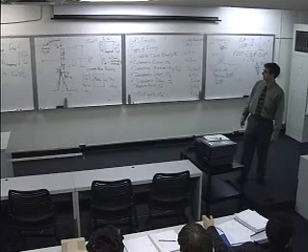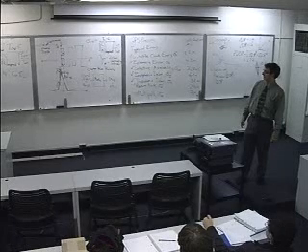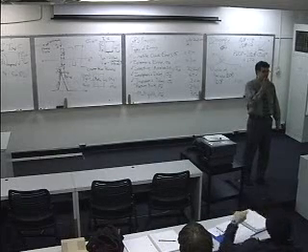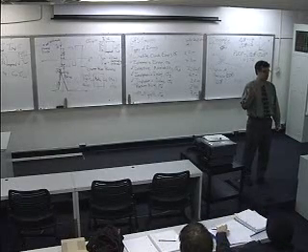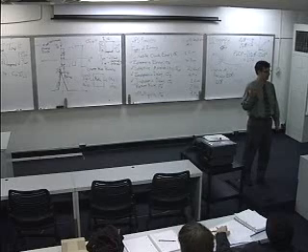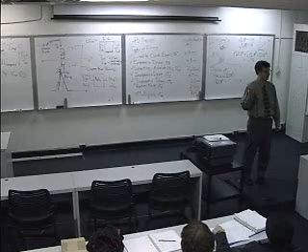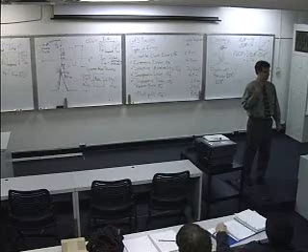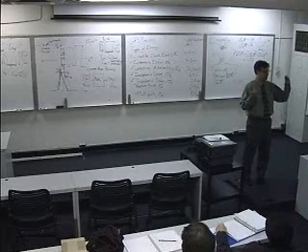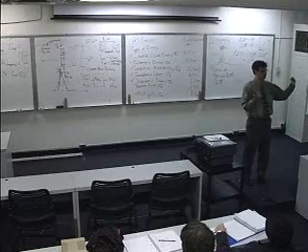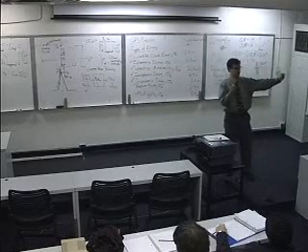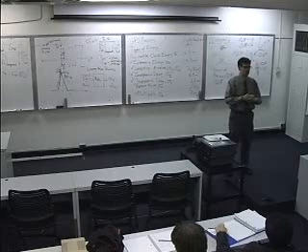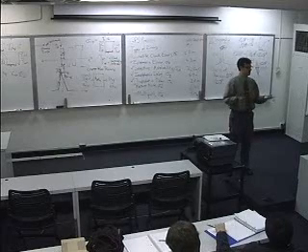Isn't there also a time dilution of precision? Time dilution of precision. In the way that GPS works, the GDOP is sort of a time dilution of precision. It's the temporal uncertainty and it's how the geometry maps the temporal uncertainty into a positional uncertainty. But you will see some systems use different terminology.